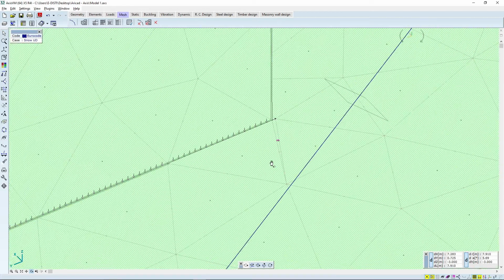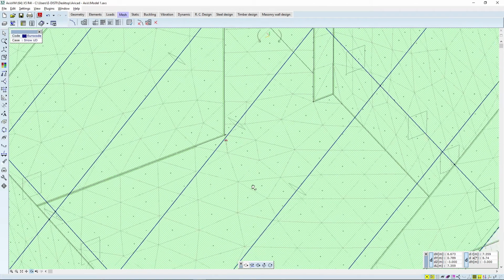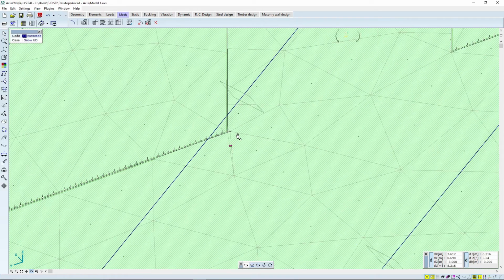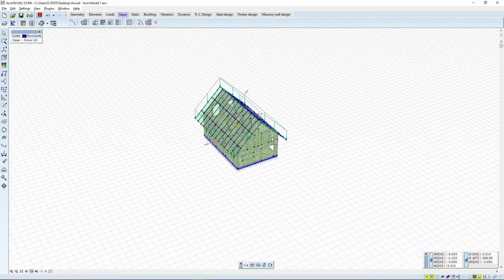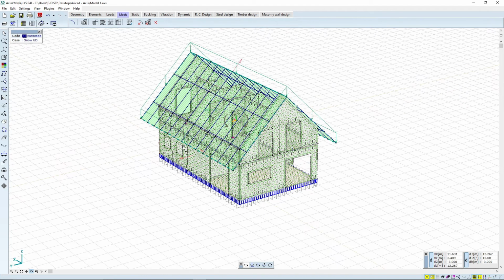It is mostly because we have a lot of activity here, and it made the mesh shape a bit different. But this is okay. So if you have below 15 or 20 heavily distorted mesh shapes, it's okay. Okay, so now we can do the statical calculation.